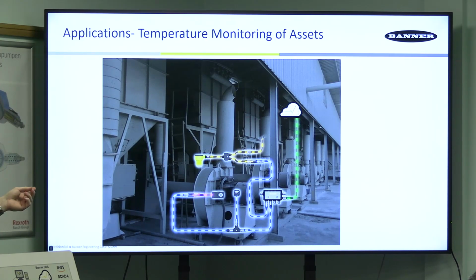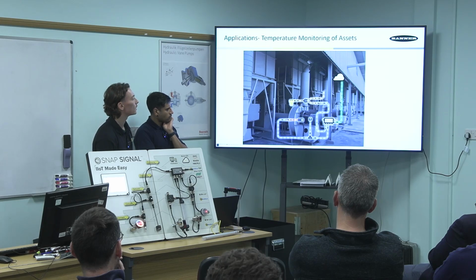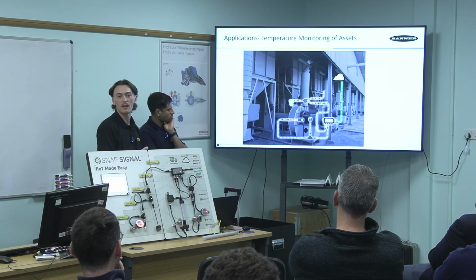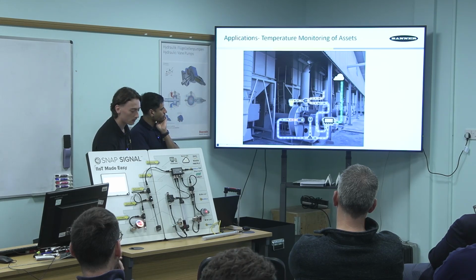And then the vibration there is for your predictive maintenance. You might see that once the motor starts up, it spikes, but then eventually levels off. And then over a period of time, as the motor wears and bearings degrade, the vibration increases, and temperature also follows suit. So you know that you might want to plan in some maintenance in the next scheduled window. And then that's all displayed out to the cloud as well.